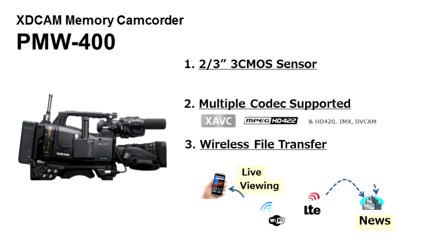The chip set that we use in this camera, which is part of the XDCAM memory lineup, is still MPEG2 because the device is made to operate using MPEG2 up to 50 megabits per second. But very soon we will activate the XAVC long GOP operation in this camera for interlace. Therefore, it's up to the end user to decide to future-proof their contents by moving to XAVC or to remain with the legacy codecs of MPEG2.